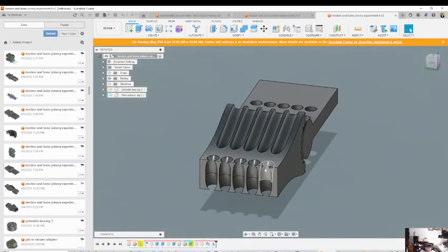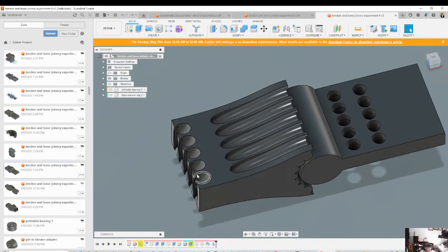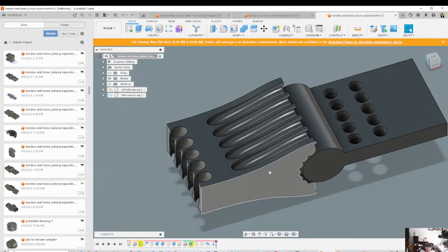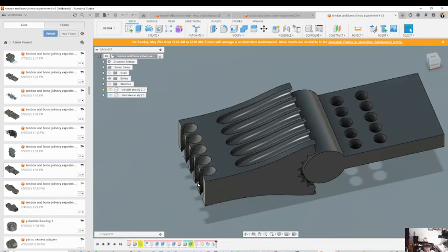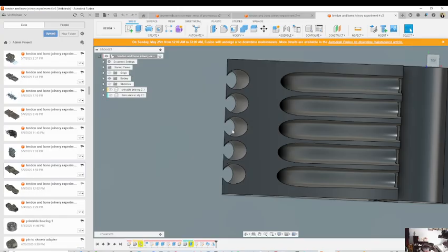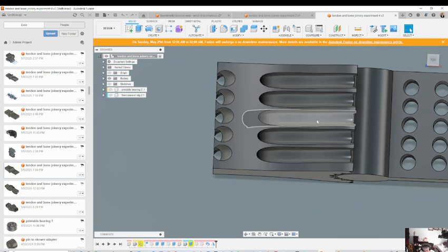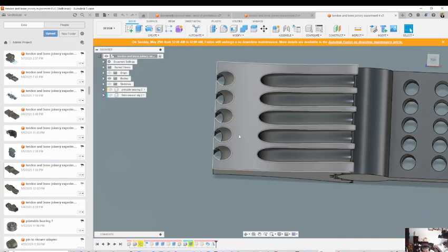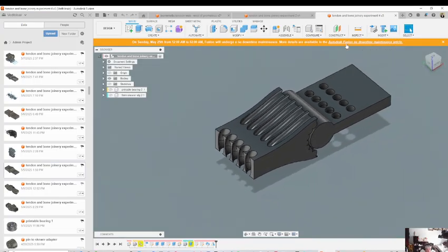I also have this outer line here, which I had to edit later on. Not very useful to have this with the outer opening. It's better to have it closed like this because I can create knots. Here I can't really make knots. Although it seems useful from the top, meaning that it looks like a cleat shape, what happens is that when you start to move the thing around, tension has a lot of variation in the system, or the string has different loads, and sometimes it bends or slacks, and then it can pop out of the cleat-like ending, so that's not good.